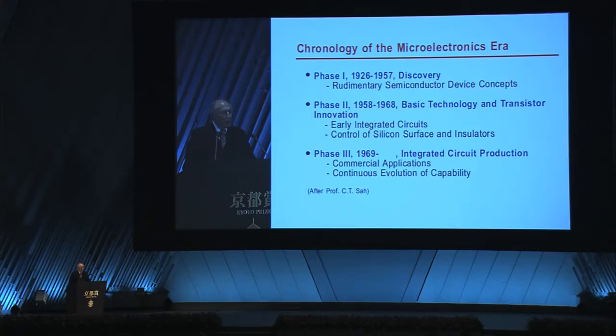We had a proposed way to build memory with our MOS technology, which used 6 transistors, 6 MOS transistors, I should say, and a flip-flop memory cell to store each bit. We hoped to integrate 128 of these memory cells in a small silicon chip.